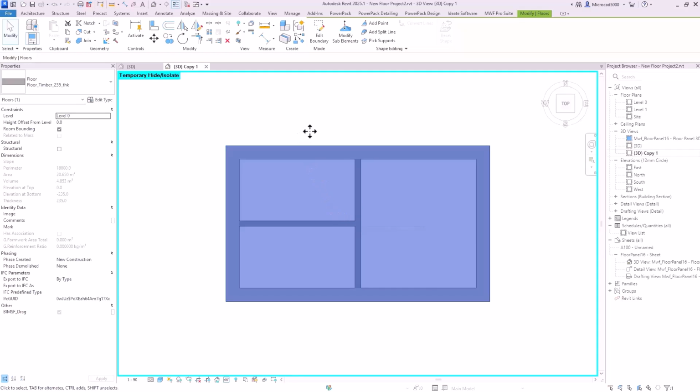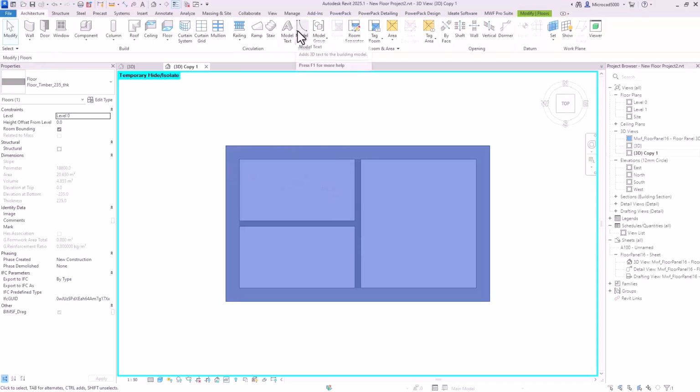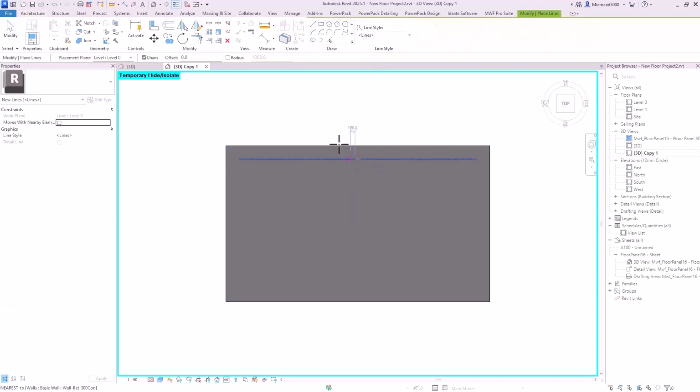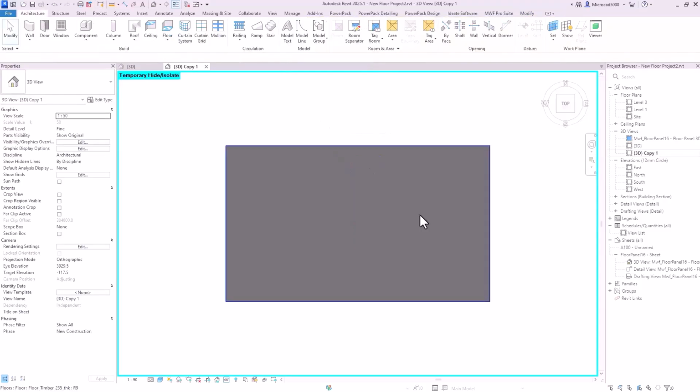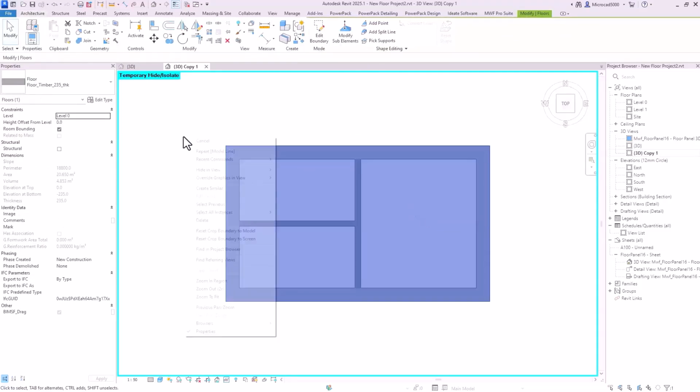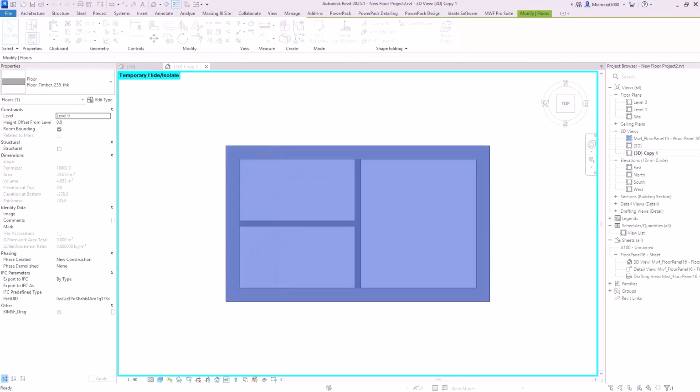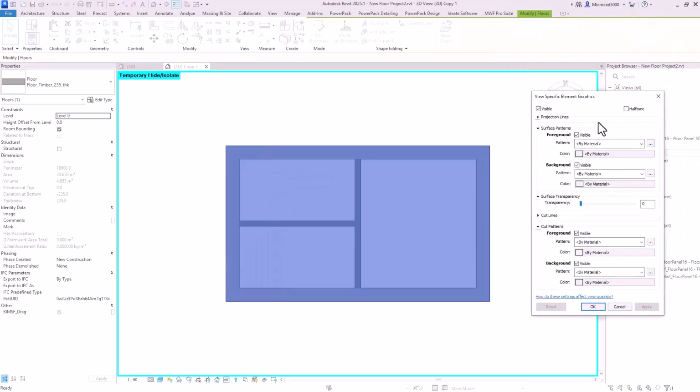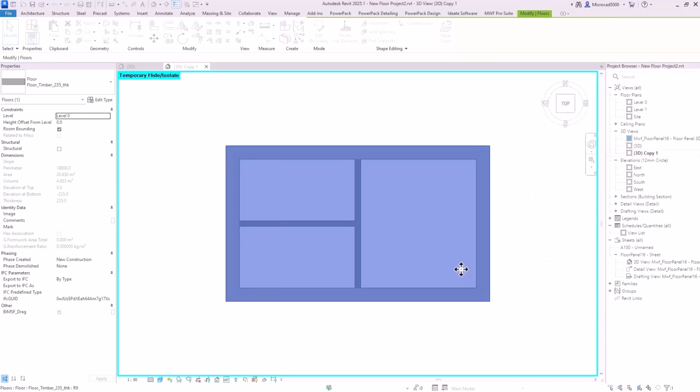You have a floor cutter tool. So to split the floor, we need to draw some model lines on the floor where we're going to do the split. So architecture tab, model lines there, look. And actually, if I just put some transparency on this floor so we can see, override graphics by element. I'm going to set the transparency, 60% will do, so that we can see the walls underneath to line up where I need to do the split.